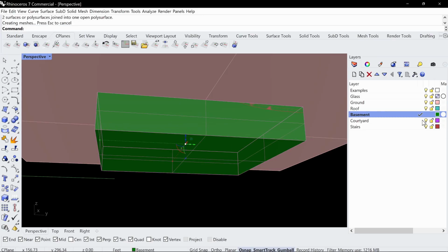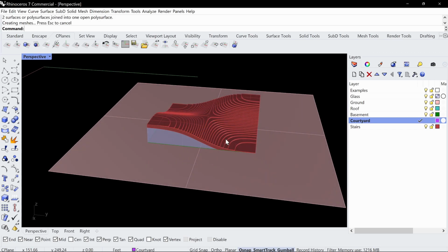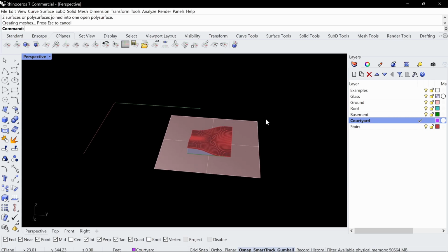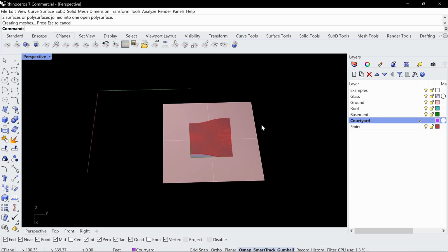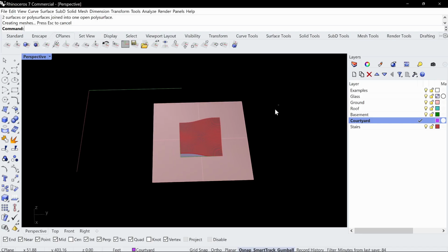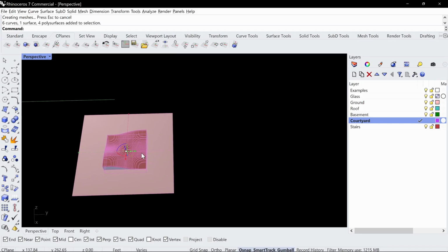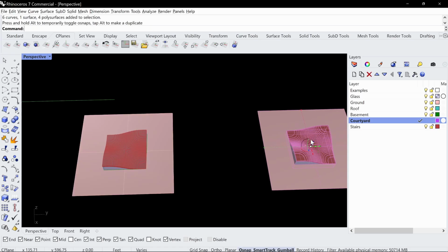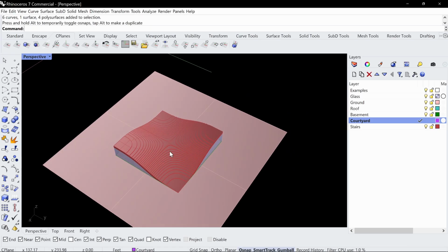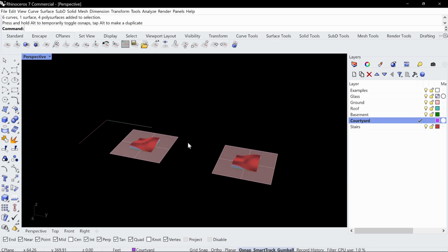And then let's give this a courtyard. Okay, let's say maybe you want to give this a courtyard. So what I'll do before I do anything subtractive, because when you do something subtractive, you're basically destroying. It's a destructive command. You're destroying your model. So let's just go here, and I'm going to duplicate this. I always like to keep my originals, because maybe in your originals, you're going to show your process, like I did this and then I did that. You're going to show your operations.